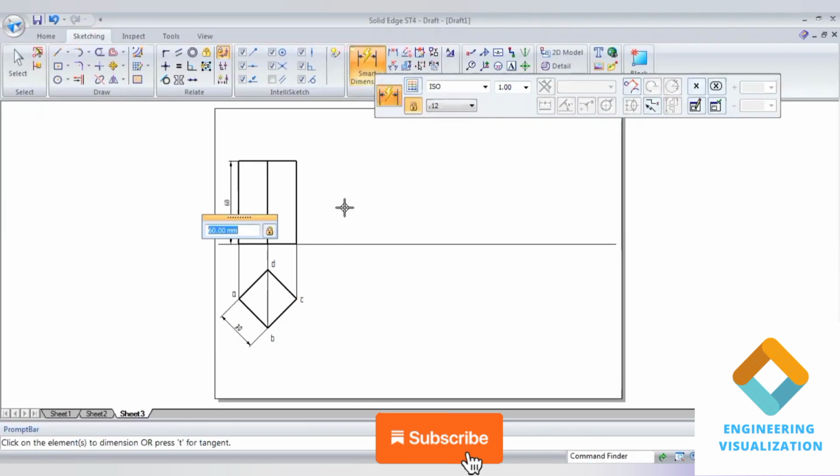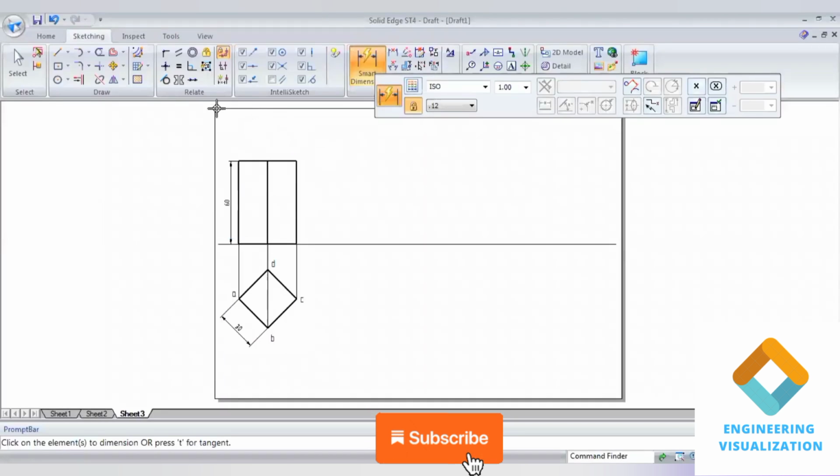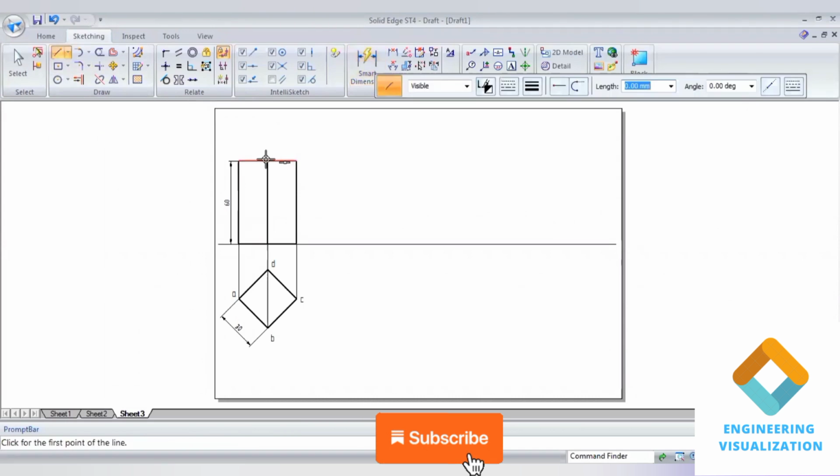Now we have to draw the section plane, which is at a height of 50 mm from the base, and it is exactly cutting the axis at a height of 50. So for that I'll be drawing a 50 mm line from the base, exactly from the center on the axis. Go to line. I am going to draw from the bottom, that will be convenient. 60 minus 50 means 10, but I will draw from the bottom, so from the bottom a 50 mm length.